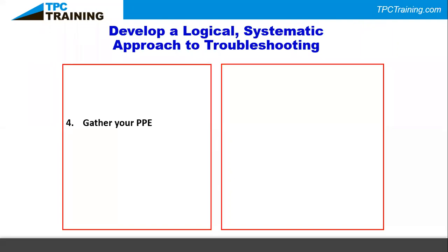On the electrical side, it also involves lockout tagout, but if you're going to be just looking at stuff and visually inspecting, or if you're doing live voltage troubleshooting, lockout tagout won't be part of it this time, but wearing full body arc flash PPE for the electrical part of this equipment, and knowing that comes with a whole set of knowledge and skills with electrical troubleshooting and understanding arc flash PPE and protection.